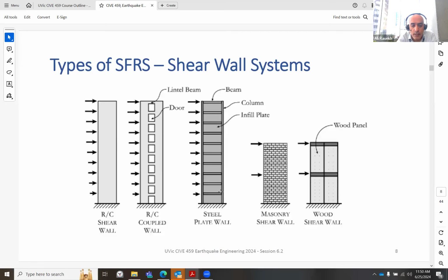even in steel high rises, we have the elevator shaft, which is practically a concrete shear wall, but this is also doable. For masonry, you can only think about shear wall effect, using a wall to resist the shear force. For wood, shear wall should also be popular because you can put a wood panel in there to resist the shear force or lateral force.